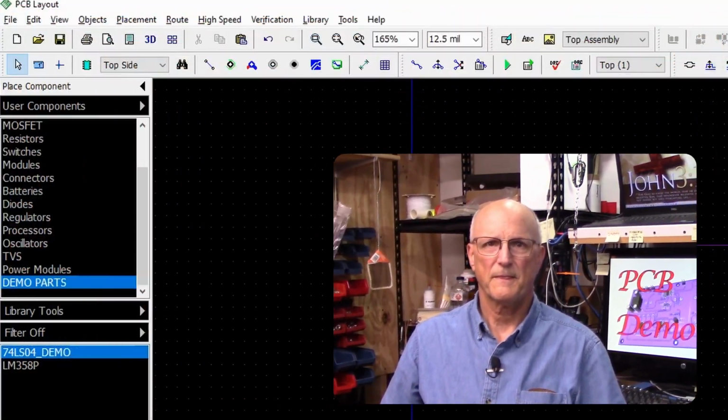I've decided to use a total of 6 mounting holes. 4 of these will be located in the 4 corners of the board, and then 2 midways down the long axis of the board. To place these, we can either carefully click on the right spots for them to reside, or we can randomly drop them and then edit their positions.